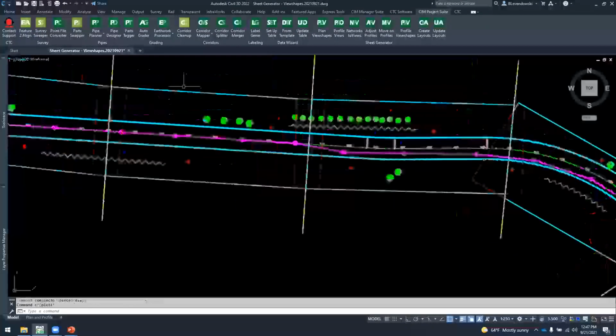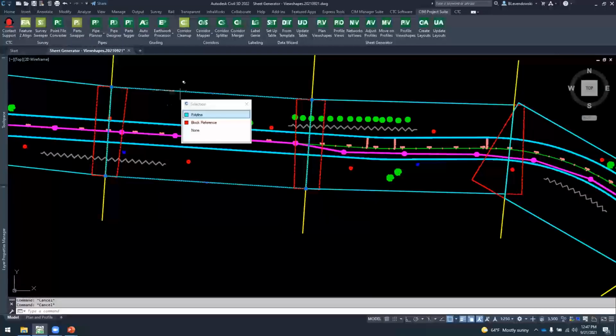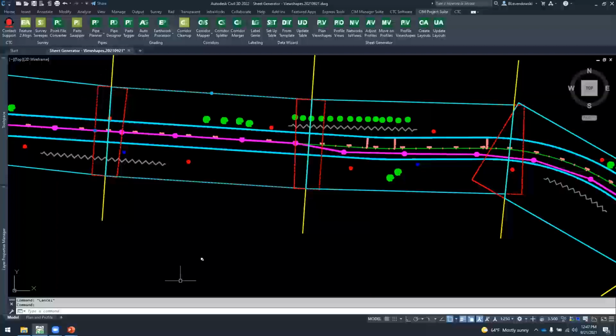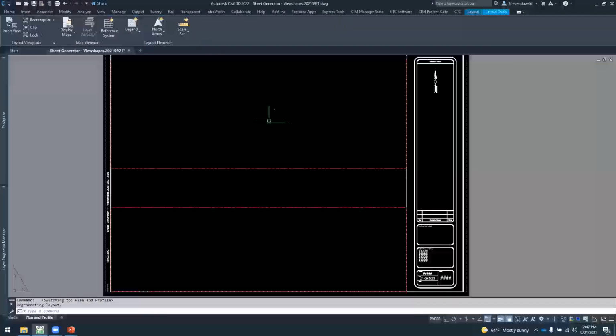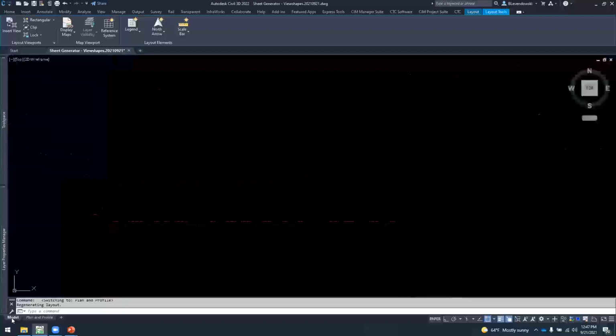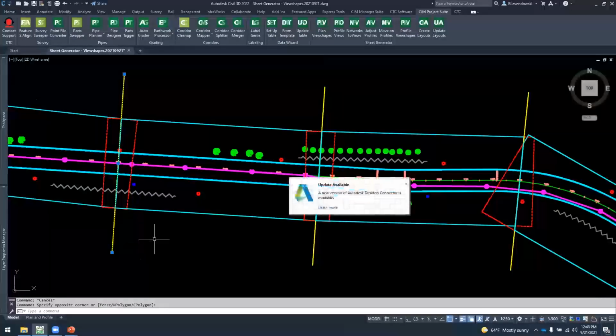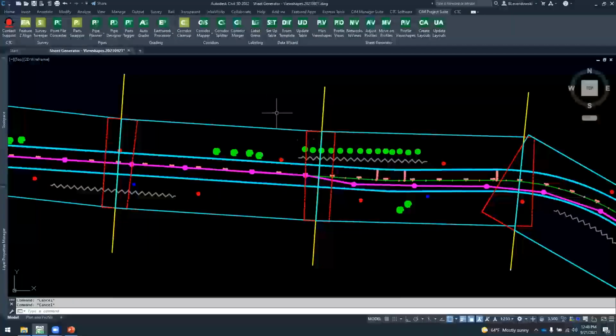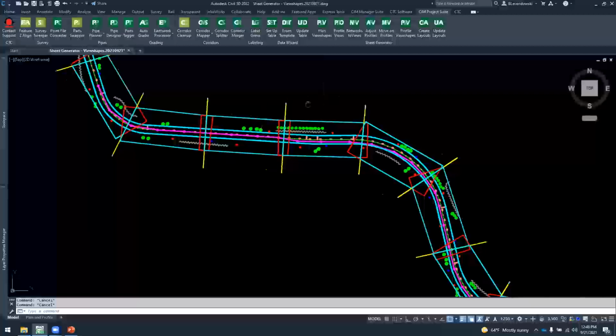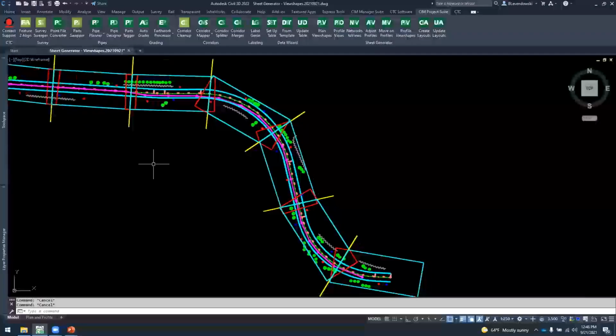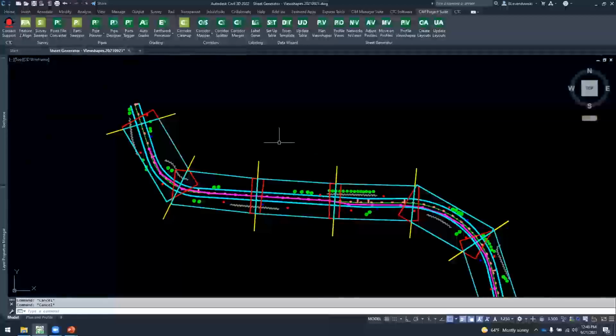Okay. So again, this is my viewport, the cyan line. The red block, that is simply a copy of what I placed on my layout template. And then based on insertion of these drafting guides, or let's call them model space match lines, we can assemble what our model views will look like. And I don't care about desktop connector right now. Okay, so that's laying out plan views.